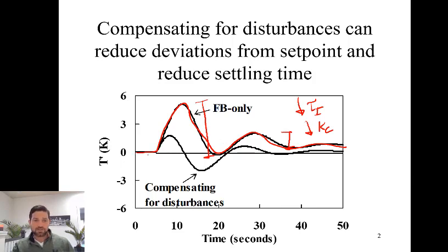The second curve right here shows an example of the same type of feedback process that has a feed-forward mechanism incorporated into it. Since this is just generic, we're not talking about the specific method yet. In this case, what we can see is that when we correct for whatever the disturbance is, the process doesn't significantly change away from its set point. Also, again, in this case, the controller has the same type of tuning parameters, but now the oscillations are around the set point because the corrective action was taken a little bit earlier due to the feed-forward mechanism.